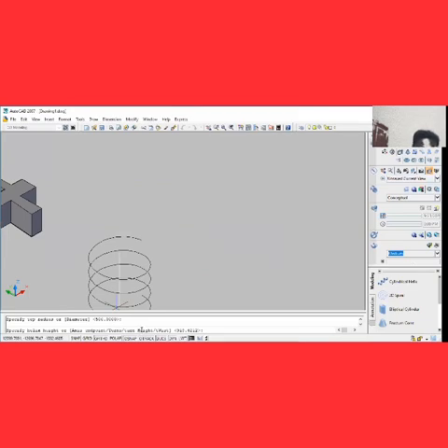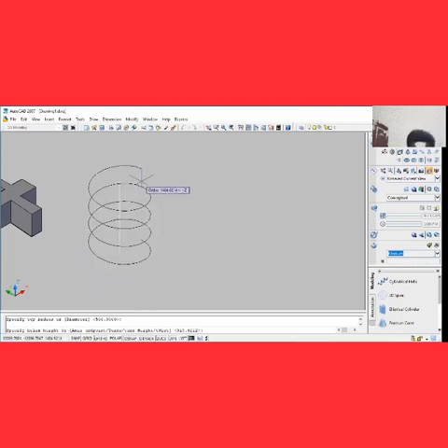You type H because H is in capital letter. And then if you want to alter the twist, it is going to be W. But we want to alter the number of turns. So if you want to alter the number of turns to, let's say, maybe about 5 or 8 coils, we'll just press T, enter.